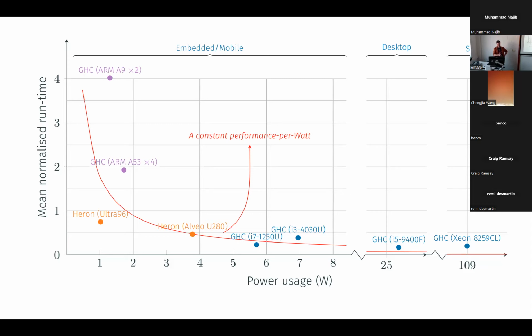So I've plotted on just a constant performance per watt, so it's 1/x scaled by something. And we can see even though most of this device is empty, doing nothing, we're getting more competitive with the Intel mobile processors. But the outlier here is this cheap implementation. It's really the only major outlier from that line. So that's suggesting that for a single core, we already have quite a good performance per watt, even on one of these like low-end FPGA devices.